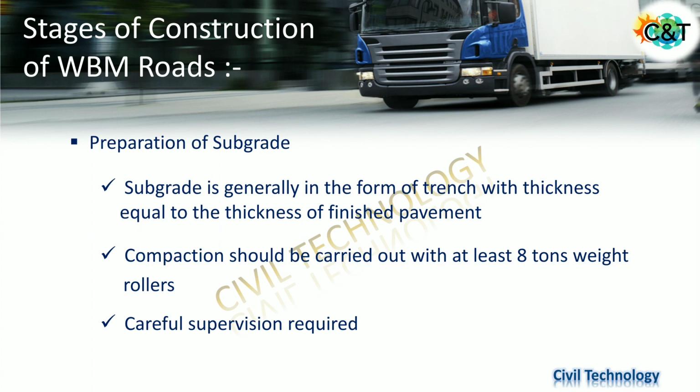Very careful supervision is needed for this, because if we do any mistake here, then it directly affects our road life, because subgrade is very similar to the foundation of a building. So very careful supervision is needed for subgrade preparation.